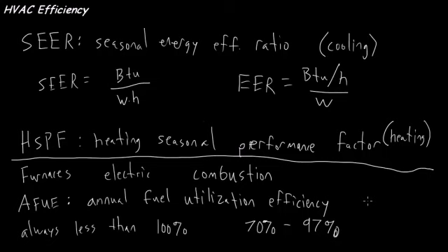One thing I should mention is that you'll see in the table that there's a range of values given for natural gas, and that's because in general the natural gas that gets piped into your home is not pure methane. Methane is natural gas, but natural gas also has various other impurities to it. It's also got an odorant added to it so that you can smell it, because methane is an odorless gas. So the heat of combustion of natural gas varies within some range depending on where the natural gas came from, because those impurities affect it.